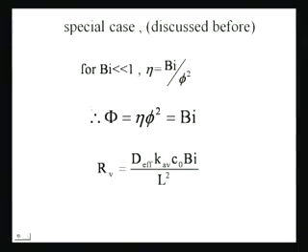So, this is exactly what we have over here. Biot number very small means the external mass transfer is limiting, and because internal mass transfer and reaction are parallel, but external mass transfer is in series with these things, if external mass transfer is limiting and is the slowest step, then the overall rate of reaction equals the rate of external mass transfer, right. These are things that we can derive intuitively, but these are very concrete ways of showing this.